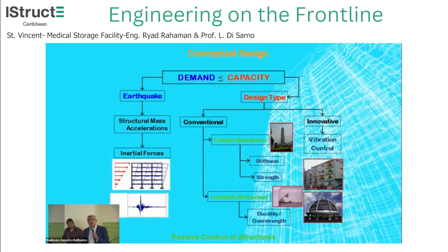The typical design is based on a conventional approach, where you generally look at elastic behavior, which could be over-conservative, not economically affordable. Or you can rely on, as we mentioned before, inelastic behavior, which means that we accept damage. This is something very clear to a structural engineer, but to other people it's not clear, even to architects. We design for acceptable damage.